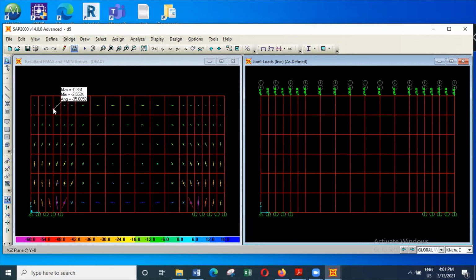So if you look at this situation, you get some loads transferred vertically downwards directly, and some other forces transferred this way. So there will be a certain concentration of stresses in this area, and sometimes whatever reinforcement comes from the column, you might continue over a certain distance, so that in the areas where the high stress concentration is, there will be enough reinforcement to carry the vertical loads.